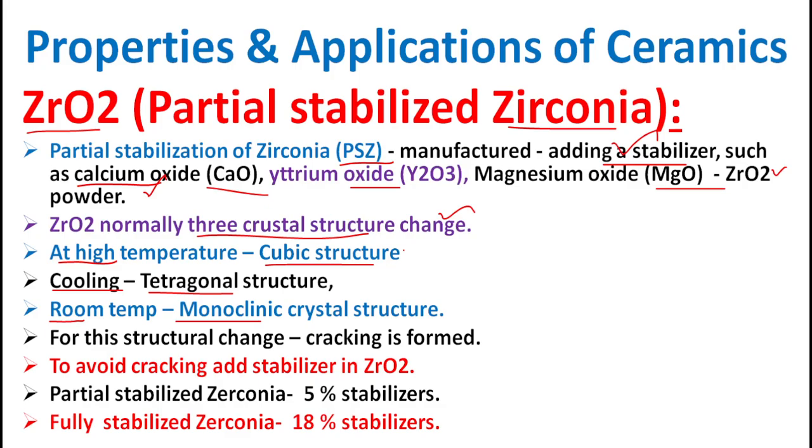If we add the stabilizer, we can avoid cracking in the zirconium oxide. During the cooling process, volume changes happen in the zirconium oxide.